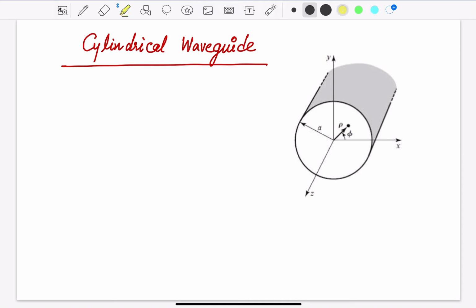We'll see today the cylindrical waveguides. Here you can see the figure. This is the cylindrical shape with radius a. We are taking some arbitrary point, so the radius is defined here as rho, and the azimuth angle is phi, correct? Depending upon the propagation, we are assuming the z direction or minus z direction.